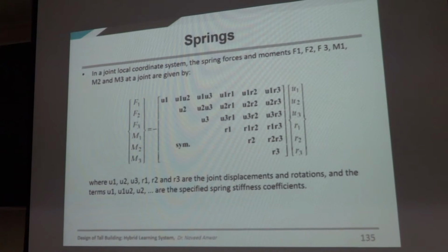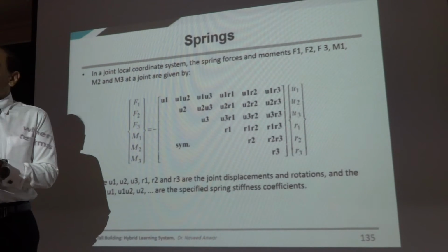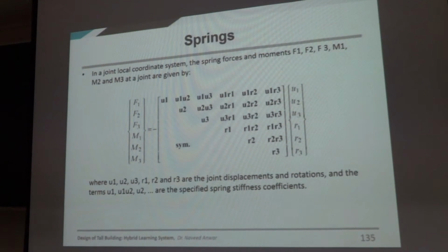In fact, in a water tank that I showed you before, the sloshing of the water, movement of the water will interplay with the natural periods and movement of the tank. Dr. Finite must have told you about liquid tuned dampers, right? Sure. So if you have a liquid tuned damper, how do you model a liquid tuned damper unless you model that whole thing also?